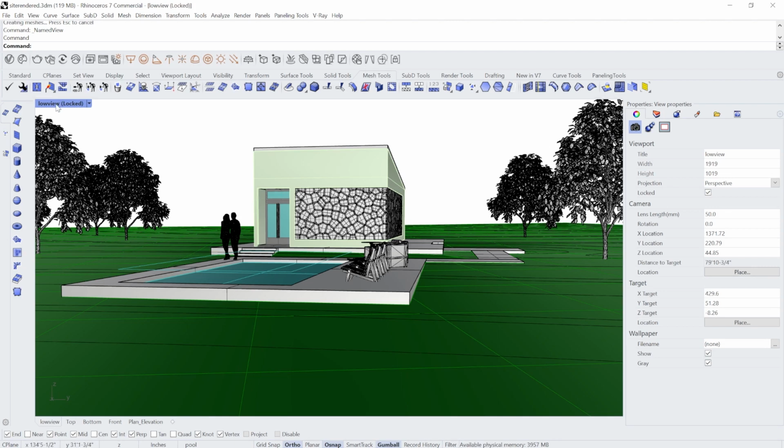Okay. And for the purpose of this, I'm going to lock the view. Essentially, what we want to work on now is the background light. There are some lights I've placed on the model, in a particular layer. I can connect that layer to a V-Ray material so I can control the lighting. Then I can add some site elements like lamps, maybe do a mesh light on the inside of the water. Also, if we just do a render right now, the water is without any reflection, so we're going to work on that.